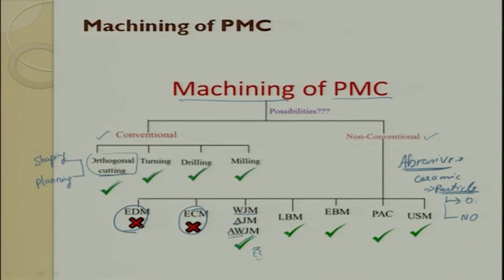The next process is laser beam machining, LBM. So, in LBM process the photons are used, and these photons are focused by a lens on top of the workpiece. The laser beam process has two mechanisms, one is called pyrolytic process and the other one is called photolytic process. In pyrolytic process, the photon, when it hits the workpiece, gets converted into heat energy, it melts and evaporates.